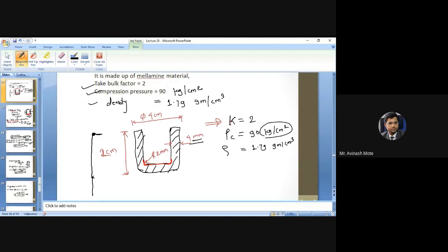Okay, and it will exactly come out of the mold. So this is the length by which we'll have to push out the product from the mold cavity. This is the pin. Getting it? So the length of the product, or the height of the product, will decide the ejector stroke required through the ejector pin.